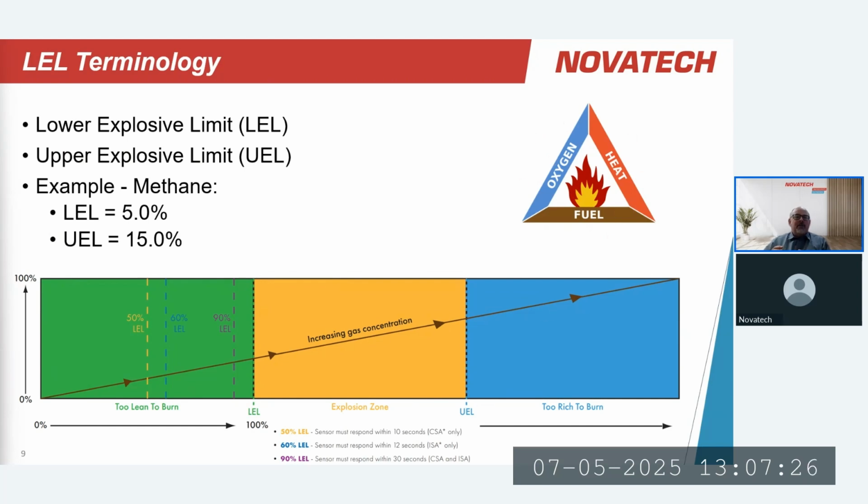For combustion to occur, which is an oxidation reaction, we need some type of fuel, something that we burn. We obviously need oxygen, and we need some sort of source of ignition. If we don't have those three components in the right ratios and the right combination, combustion doesn't happen. So if I don't have enough fuel, I'm below the lower explosive or lower flammability limit.